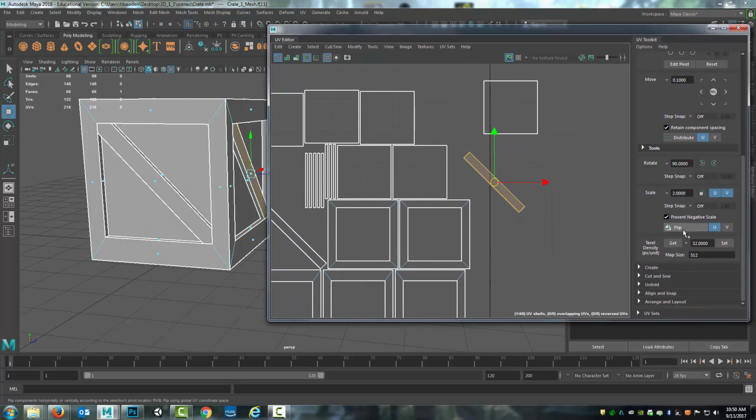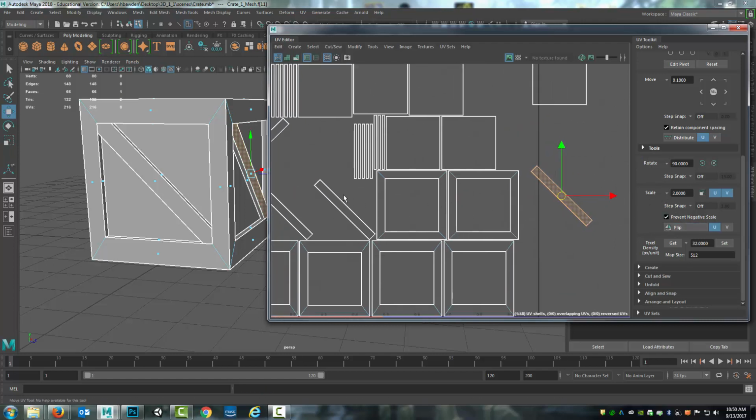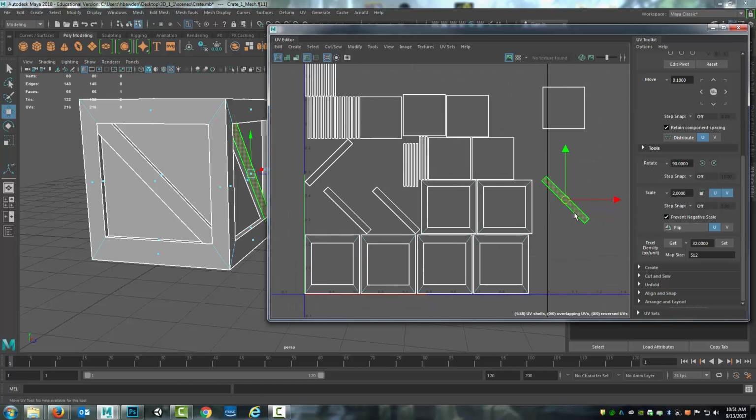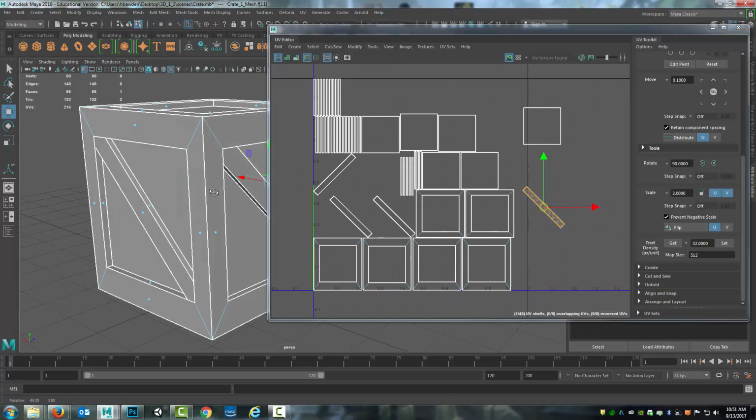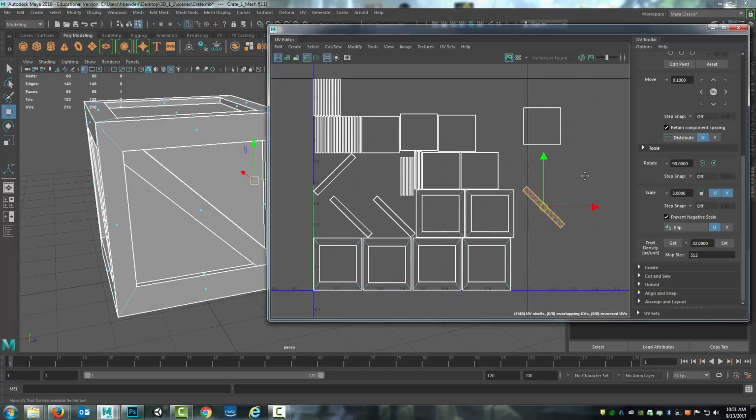If I flip this, and so it's on the other side, especially when you get into advanced textures such as normal maps, it can actually reverse things. So for example, if we're painting the texture for all of this wood and the wood grains are going in, and I have one of these that's flipped over, it'll cause it to come out and react differently than you might expect. So you want to work with everything in the direction that it's set up.